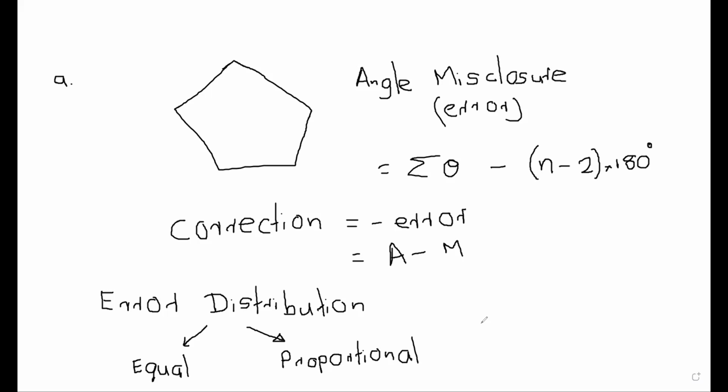Therefore, we usually use angle measurements as equal distribution. When we are correcting for angle measurements, we use equal distribution. For length correction, next time we consider the length also. For the length correction, we use proportional, assuming when you measure larger distance, you create large error.